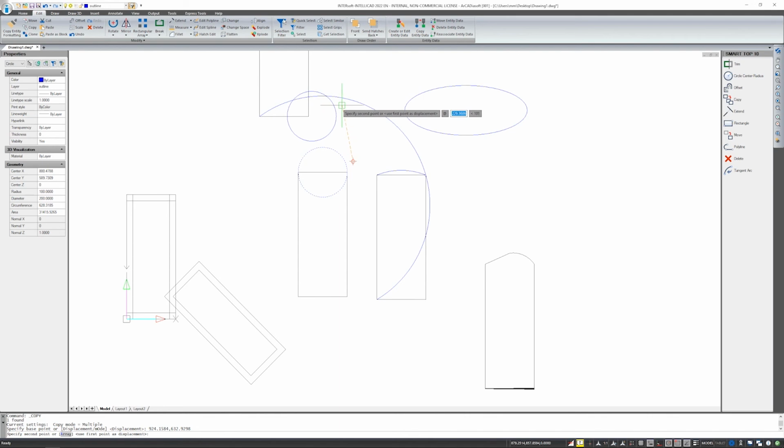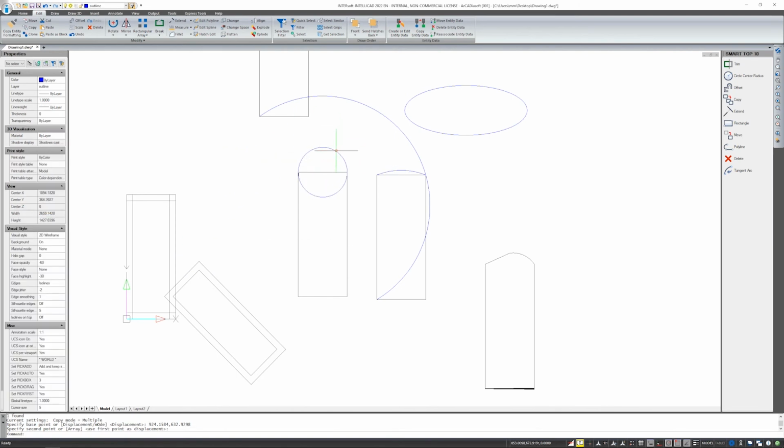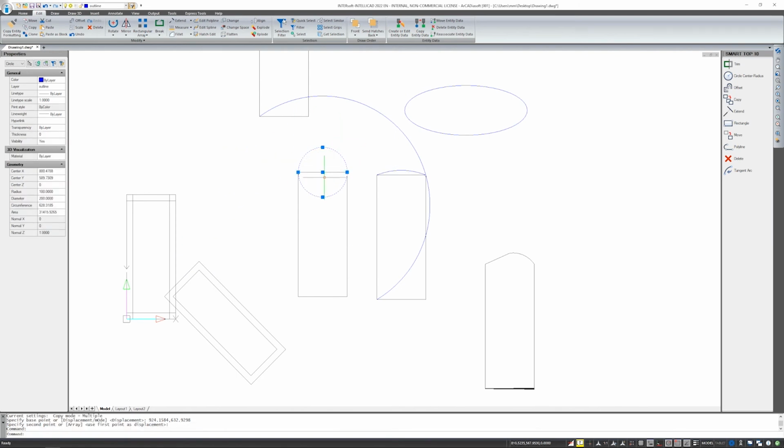So if you are copying or moving anything, because moving is similar, the base point is very important. If I want the circle to be duplicated on the rectangles that have already been entered and to be introduced in exactly the same way, I can use either the center of the side or, for example, a corner. And then I copy exactly as it is entered here. If it needs to be copied to another place, please remember that the characteristic points later on give us the opportunity to introduce the circle to a specific place.